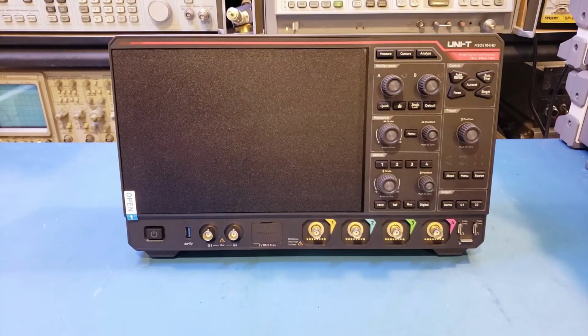Hi, what I have here on the workbench today is a UNI-T MSO5104HD mixed signal oscilloscope. It's not just yet another oscilloscope. The MSO5104HD offers 12 bits vertical resolution and a whopping 1 GHz analog bandwidth with 5 gigasamples per second sampling